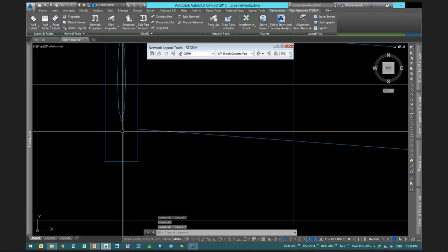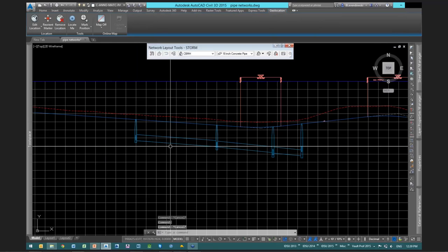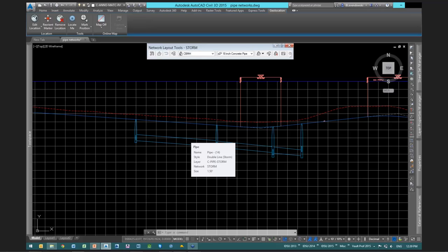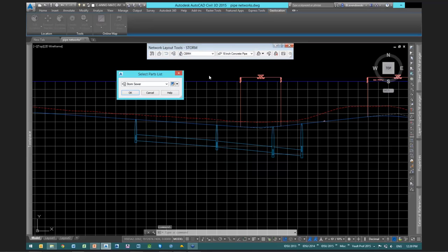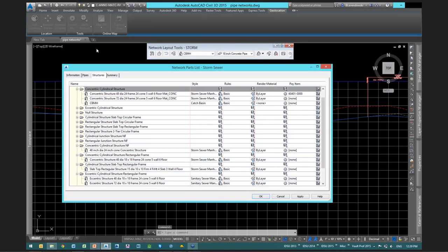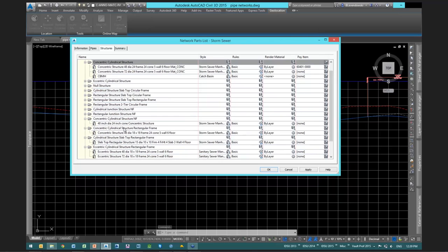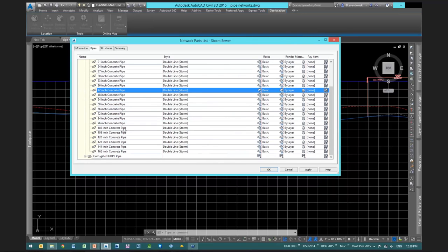So use rule sets a bit to define default, kind of ballpark starting parameters, right? A sump depth of 0. Okay. What other kind of things would you set? Well, let's dive into that parts list again and look at those rule sets. Okay, if it's pipes, for example, larger pipe can go in at flatter slopes. So instead of just one rule set here, we can have multiple rule sets.